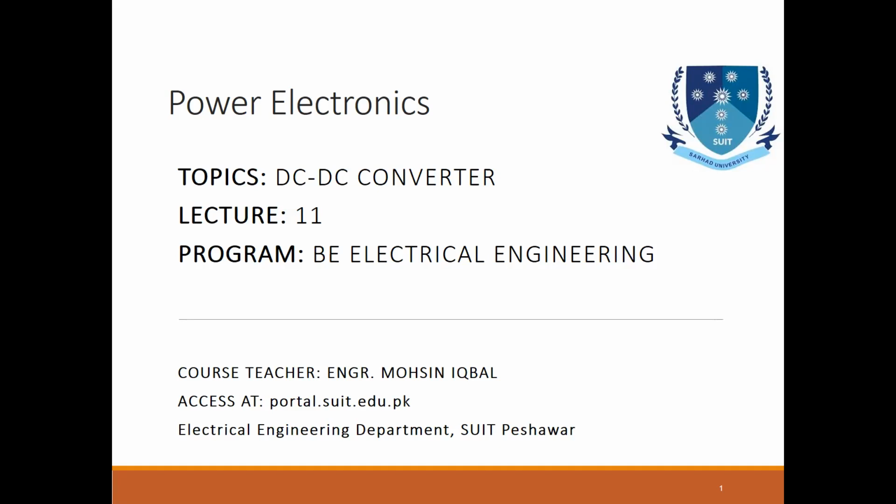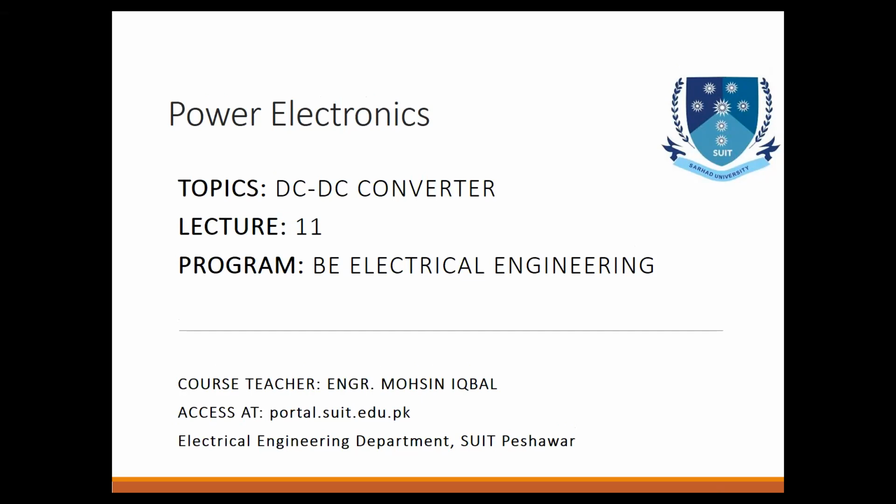So after that, we are going to study the DC to DC converter. Basically, DC to DC converters are those converters whose input is also DC and whose output is also DC. Normally, the DC supply cannot be stepped up or stepped down through a normal transformer because of no frequencies. So special circuits or converters are used in order to step up or step down these voltages. In this lecture, we will study these converters, how we can step up or step down an input DC voltage to an output of the same DC voltage at different values. That's our today's lecture.